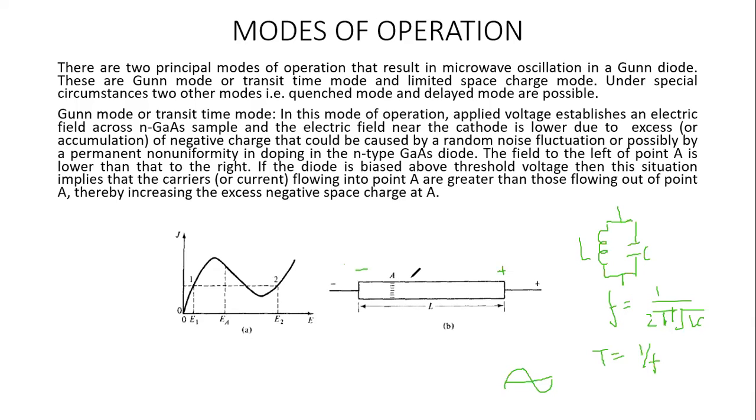So electrons on the right hand side will be moving with lesser velocity, and the electrons on the left hand side will be moving with faster velocity. What is going to happen? The electrons coming from the left side are going to jump to the upper valley, and their velocity will drop. So now on the right hand side the slow moving crowd is there, and from the left hand side a crowd moving with faster velocity is coming. Definitely these two crowds will merge, and a huge crowd will be formed.